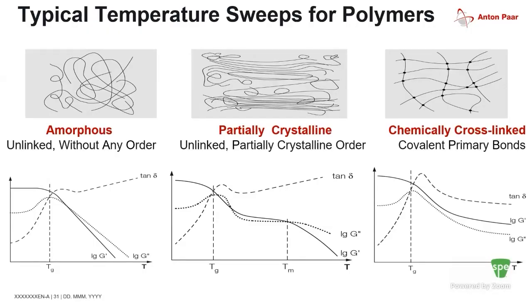So it goes from a solid to a liquid, and becomes more flowable. Whereas in partially crystalline materials, where you have some structural behavior, you'll see it behave like a solid up to the glass transition temperature. We see a plateau, or rubbery elastic plateau region, followed at higher temperatures by the melt temperature, where the sample transitions from a solid to a liquid with increasing temperature.